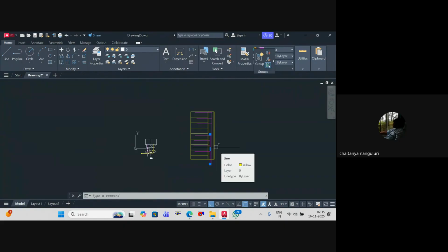So below floor level, at the main branches or anywhere, you can go for an orifice plate, which will reduce the pressure like a pressure reducing valve. You can use the orifice plate to reduce the pressure. So at multiple locations, we'll provide an orifice plate. That is to the branch? Not to the vertical, to the main branch we will provide it.